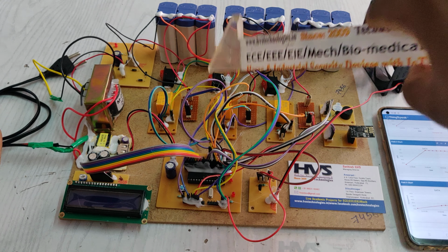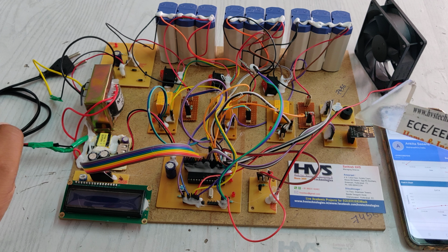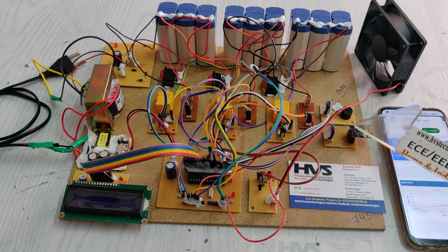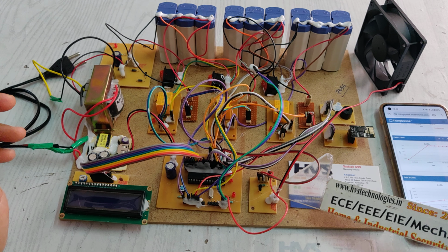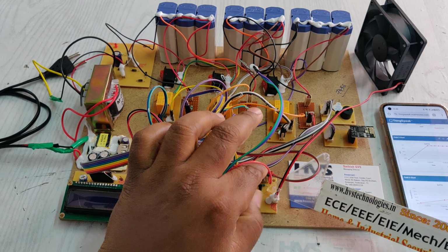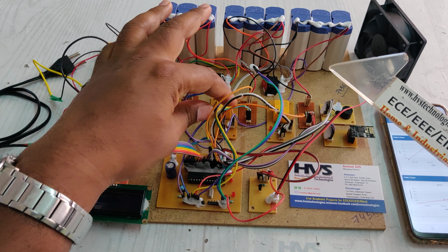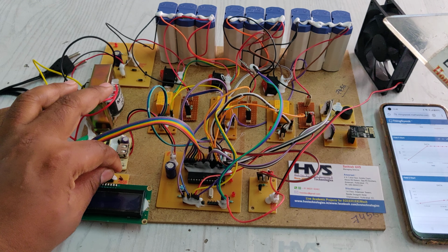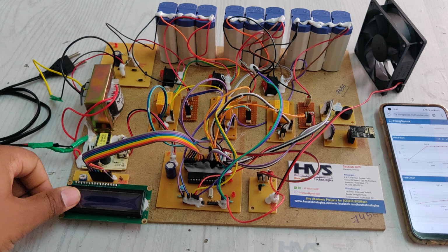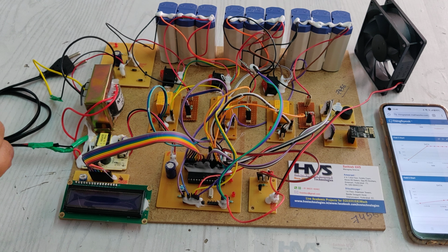We are making use of these relays, and these three are the voltage and current sensors, and this one is a buzzer board, and this one is the ESP8266 Wi-Fi module. And here is a transistor board which will act as a switch to control this fan whenever the temperature increases above the threshold value, that is 45 degrees centigrade. Then the system will control this fan with the help of this transistor board for thermal protection. This one is a PIC16F73 microcontroller, which is the main processing unit and brain of our system.